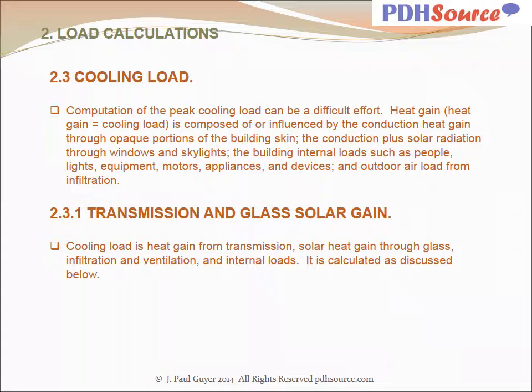And so with windows in a building, there is both transmission cooling load and there is cooling load due to the solar heat gain by virtue of the electromagnetic radiation from the sun passing through the glass and heating people who are inside the building.